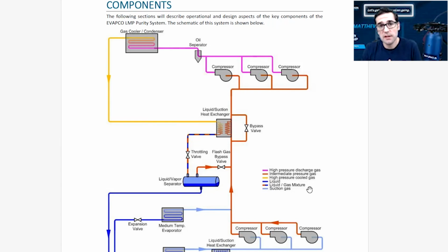Technicians in the field don't know. They've got a bunch of pipe. They know it on the schedule. It says 2 and 1/8, 1 and 1/8, 7/8, whatever it is. They go and grab that pipe, put it in, and start brazing it up. But the problem is that pressure rated pipe is not correct. This is something that is very key to understand, especially if you're in construction.